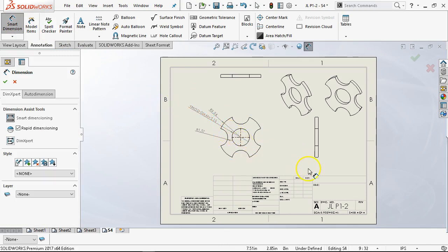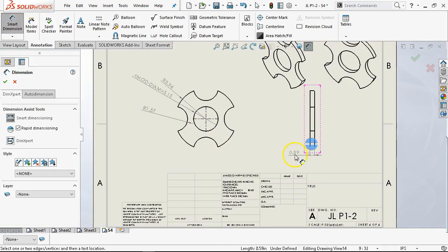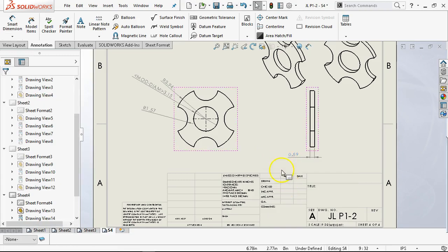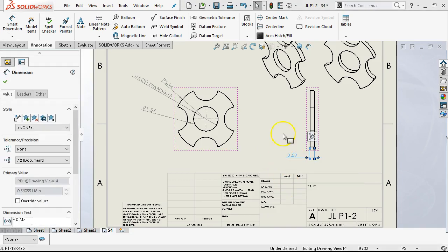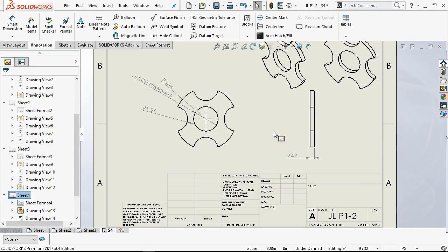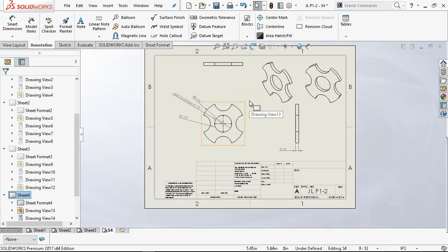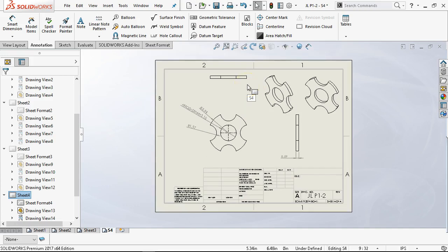Yes. When you make the dimension layers, can you save those so that you don't have to do it for every drawing? It's built into the template at that point. So when you're setting up a template, doing the title block, doing all of the things that you want to run in the background, that's also the time to set up at least the first couple layers.